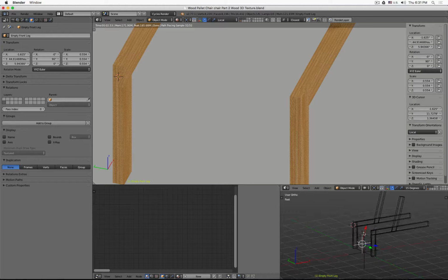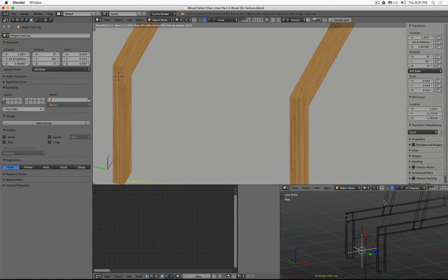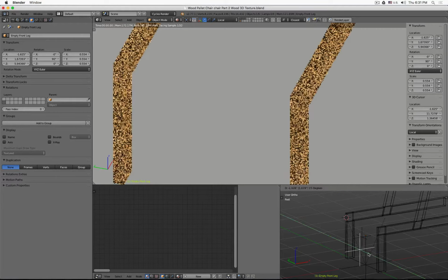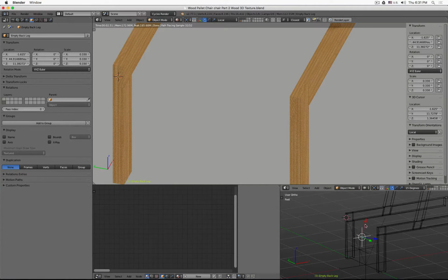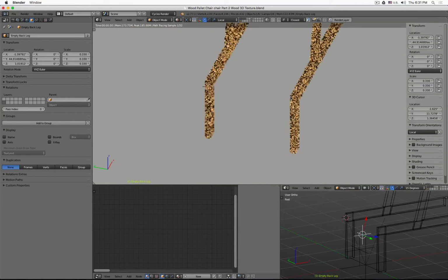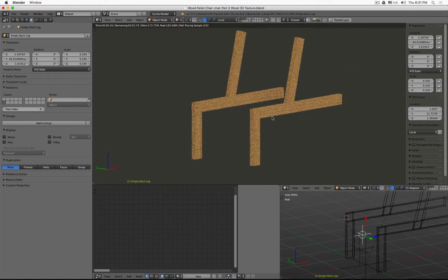So you see now, I would have to do the empty thing for every element that uses a material. Which then later, if I want to adjust maybe individual objects in 3D view, I could just move around these empties. And I don't have to go into each material and adjust something there via values. Visually, I can drag elements that then drive changes inside the material. I don't require you to try this one out. Maybe just take a look if you're curious, and then you can see if it's something you even might rather prefer working with or not.